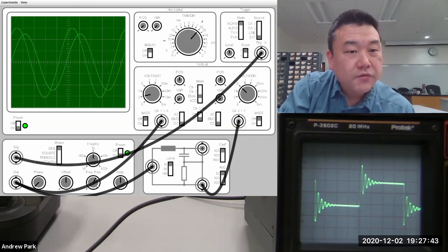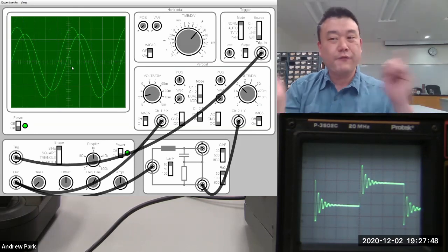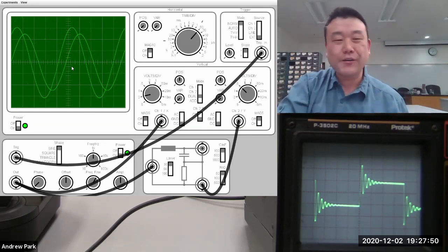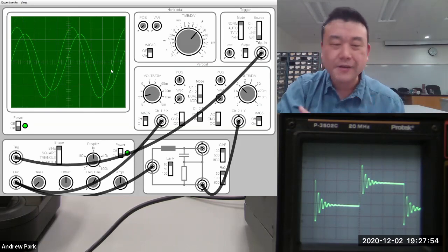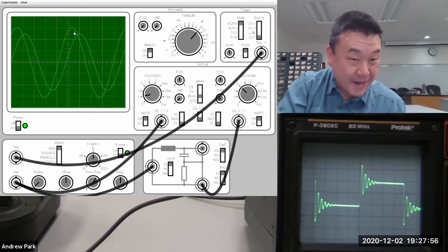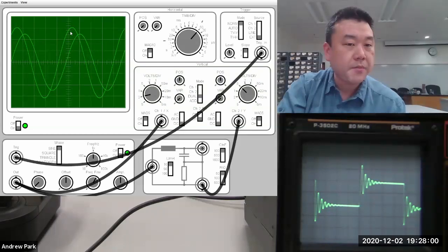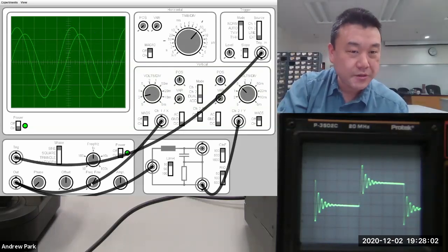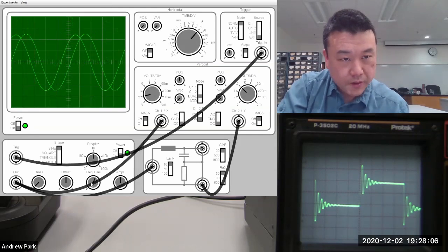So as it reaches resonance, the phase shift that you saw reverses sign. So current was, I think this is lagging, whatever. Current was on this side of the voltage, and as it goes through the resonance, you will see the peak go to the other side of voltage. So yeah, around here is where it reaches resonance.